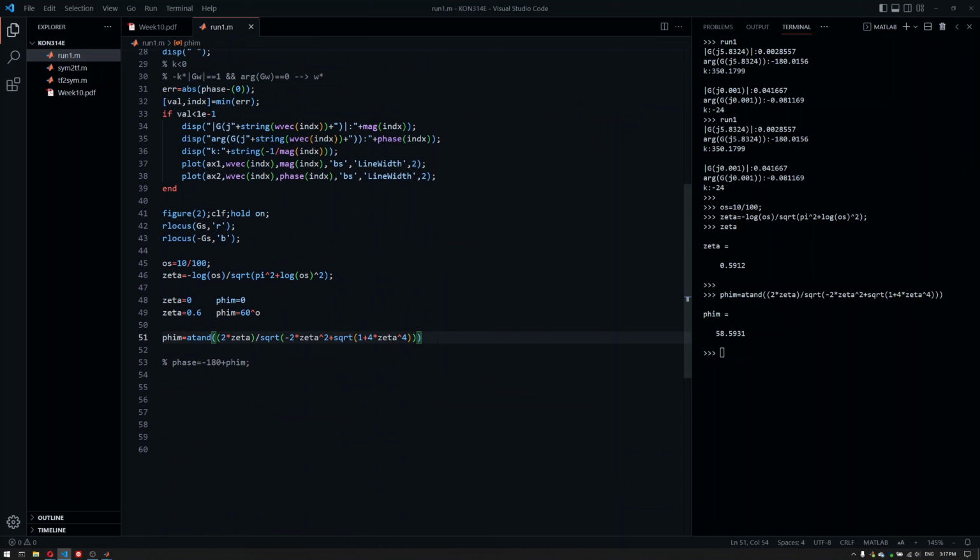We don't have a second order transfer function here, but we will try to use this no matter what. So in the Bode plot, we don't really care about the order of the system because the model of the system is not really used that much. You have a Bode plot and then you forget about the transfer function. You just have the Bode plot. For that reason, on the Bode plot, we will search as if it is a second order transfer function.